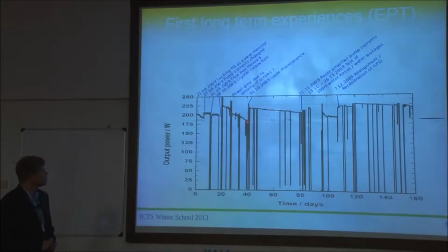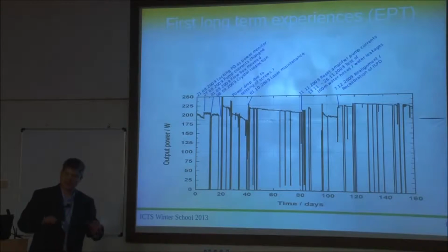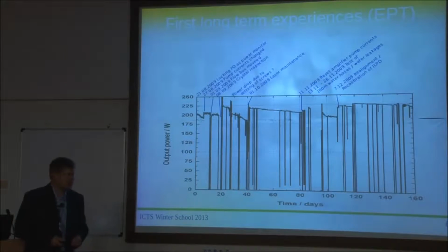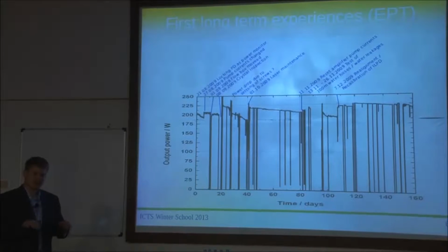This, for example, is where we figured out that the system actually needs a couple of days to settle down. So when we install it first, everything is aligned, we turn it on, then it actually needs a couple of days to let the components settle, let all the screws settle and so on. And that's when the power went down here. So we had a little maintenance phase here, aligned everything back, and then we saw that this power drop is much less.